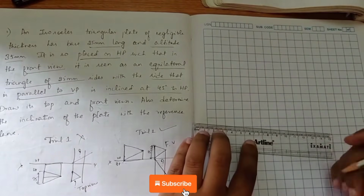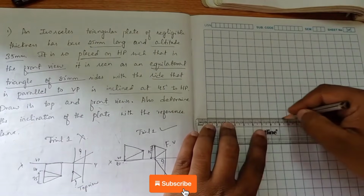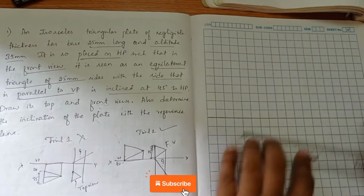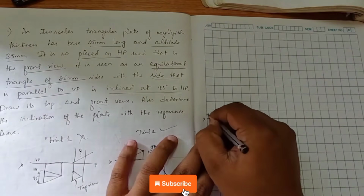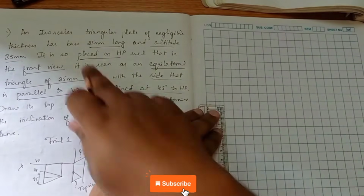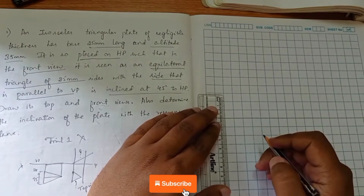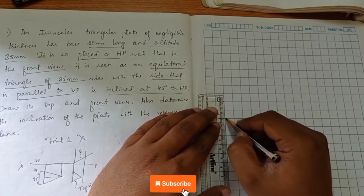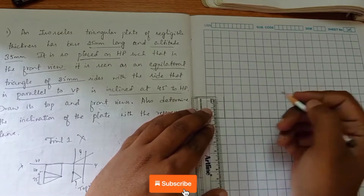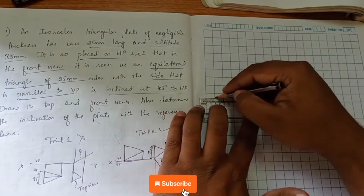So first I will draw an XY line. Drawing the XY line is compulsory. VP, HP. So first I'm constructing the isosceles triangle. First I consider the base edge, that is 25. After constructing the base edge 25 exactly, I will show the dimensions initially.